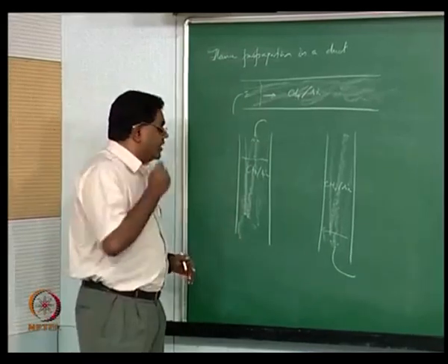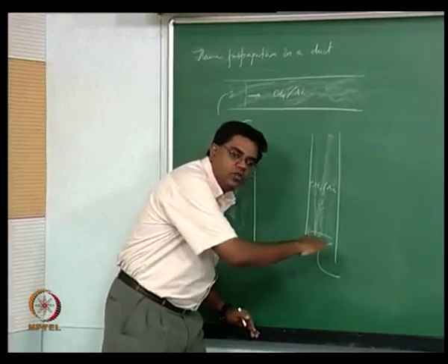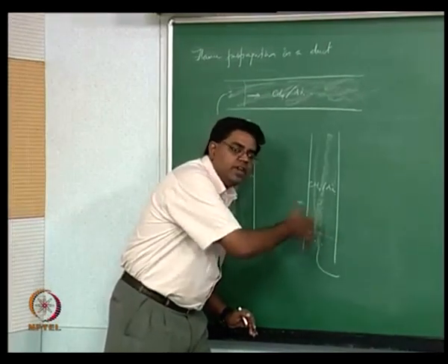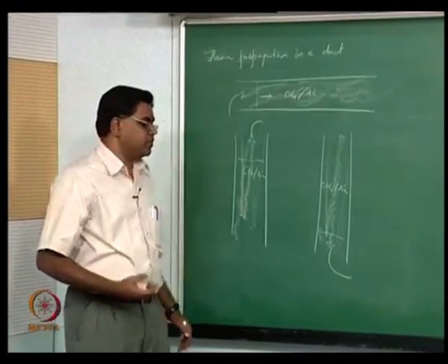All these things eventually lead to the formation of things like cellular flames. That means you no longer have a flat flame at all, the flame gets highly wrinkled, okay, and then you get into what's called cellular instabilities.